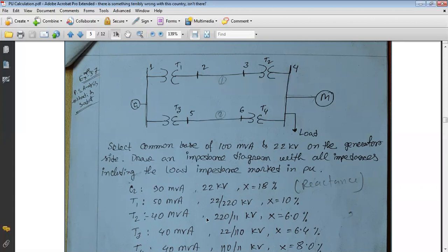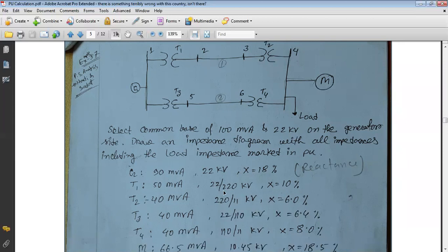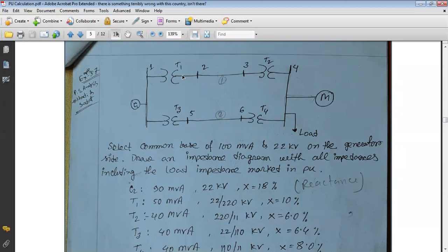সিমিলারলি আমি যদি T2 এর কথা বলি, তাহলে 11 কেভি এটা হচ্ছে লো ভোল্টেজ সাইডের রেটিং। সো 11 কেভিটা বসবে যে পোর্শনটা ট্রান্সফরমারের লোডের সাথে কানেক্টেড সেই পোর্শনের রেটিং হিসাবে। আর 220 হাই ভোল্টেজ পোর্শনের রেটিং এটা বসবে ট্রান্সফরমারের হাই ভোল্টেজ ট্রান্সমিশন লাইনের সাথে। তো কোশ্চেনে তোমাকে 220/22 থাকতে পারে, তো তোমাকে কোনটা কোন পোর্শনে বসবে সেটা এভাবে আইডেন্টিফাই করে নিতে হবে।